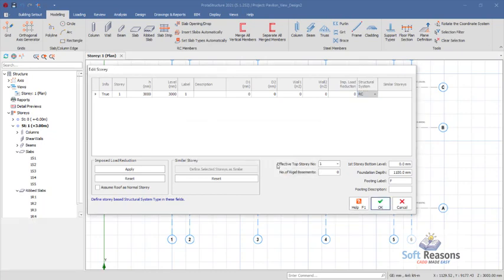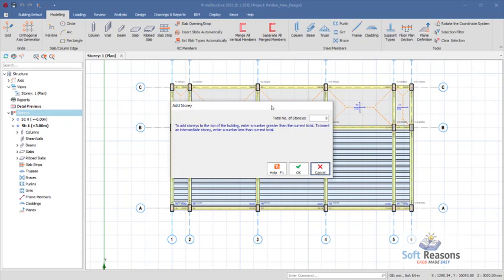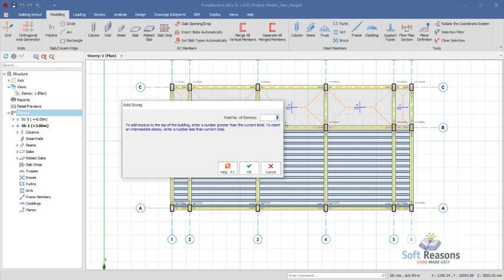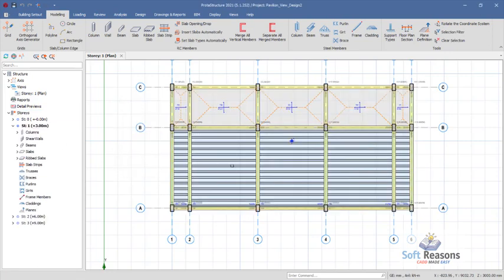And yes options. Since we are having two floors, we want to as well generate stories, or insert stories, as first. So you click on insert stories. We have two floors plus the roof level, which is going to be 3 floors. So you key in 3 right there, click on the OK option. So you navigate back to the populated story, which is story 1 right there.